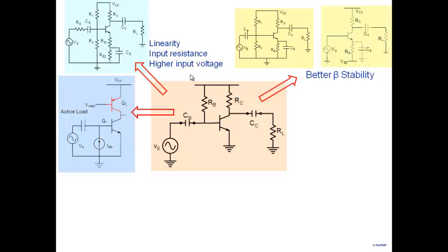One of them we'll look at is that this particular amplifier, we'll just see in a minute, has, if you want high gain, you will require very high supply voltage. Or let's say if you have a portable application and the supply voltage is very low, let's say VCC is only 1.5, then you get very low gain. So that's the problem with this particular stage.